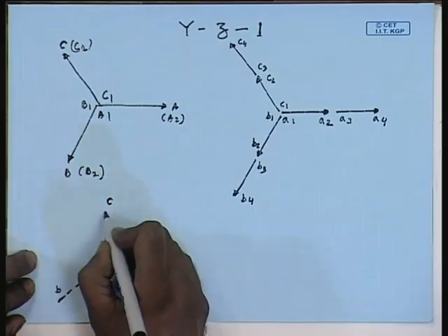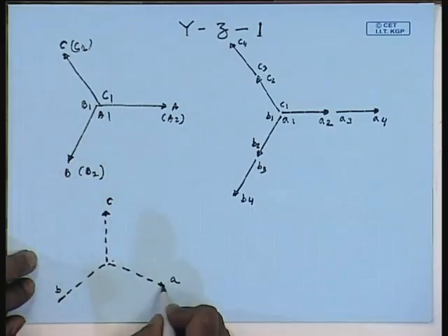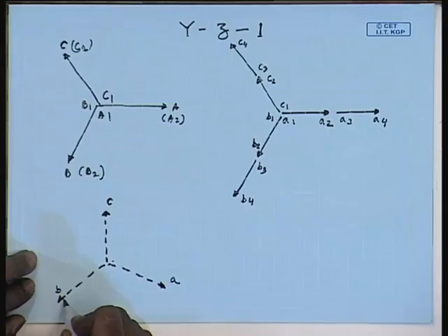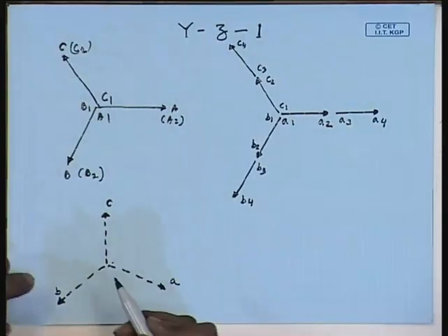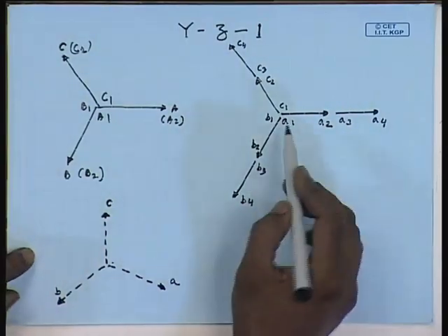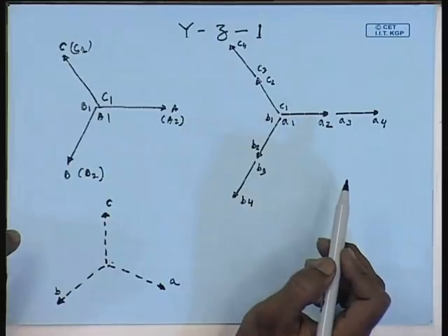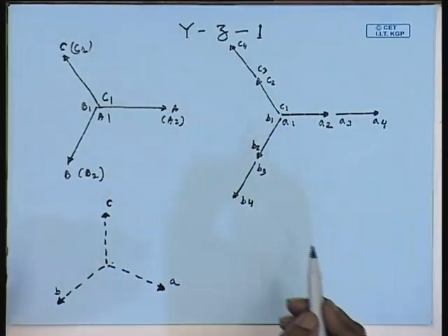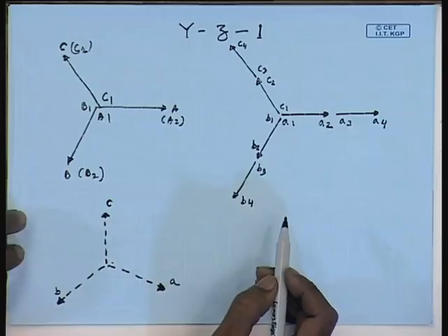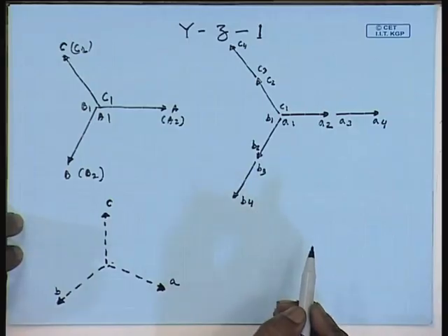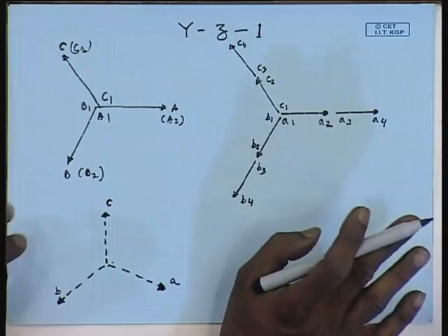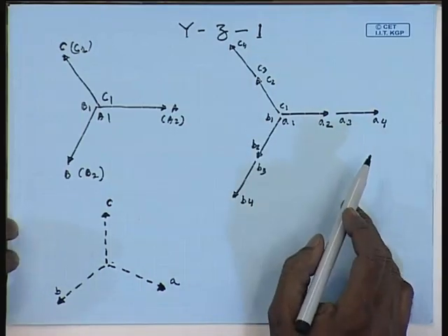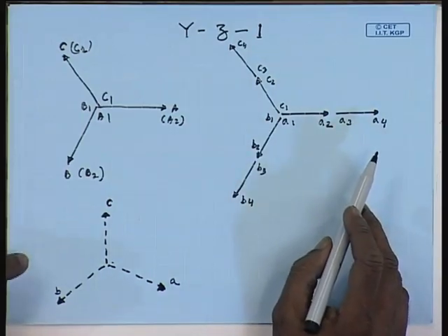How do we obtain this? From using this set of winding voltage phasors and with the constraint that the last leg of the winding should be made of the same phase, that is A phase should be either A1 A2 or A3 A4, usually it will be A3 A4.